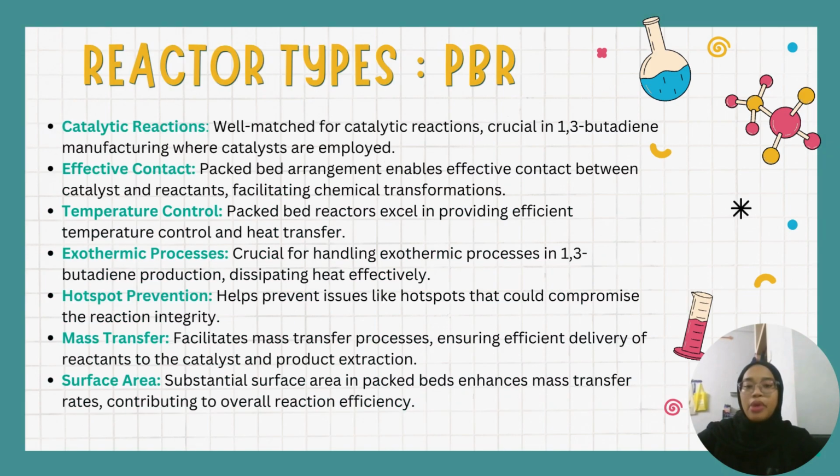Next is the reactor type. We chose a packed bed reactor because it is well matched for catalytic reactions and enables effective contact between catalyst and reactants, facilitating chemical transformation. Packed bed reactors also excel in providing efficient temperature control and heat transfer. The PBR is crucial for handling exothermic processes in 1,3-butadiene production, dissipating heat effectively.